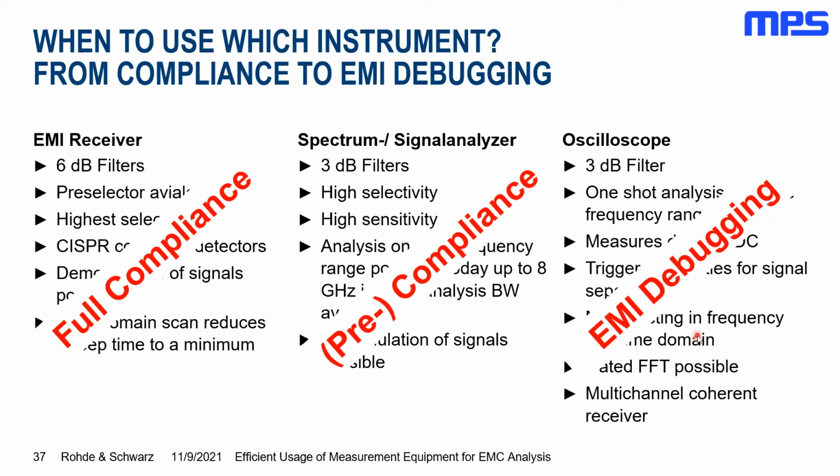are highly recommended. And as we are talking especially about power applications in this webinar series, in most cases you'll have your oscilloscope already mounted on your desk. So my highest recommendation to you would be, please think of using the FFT inside the oscilloscope, because nearly every oscilloscope that has been sold in the past 15 years has a more or less usable FFT implementation. So at least you'll be able to see if there are some frequency components running around in your design that you might not expect.